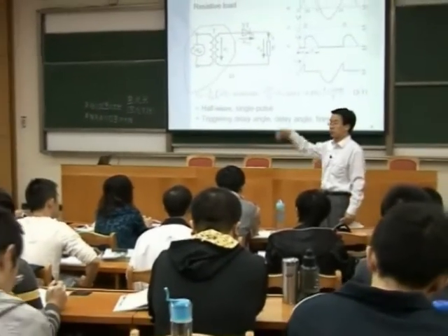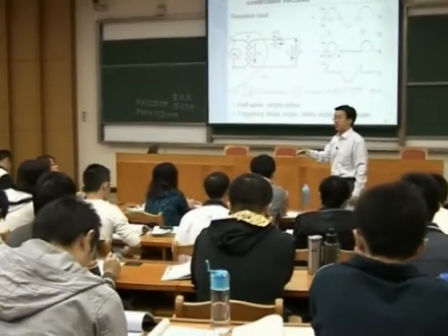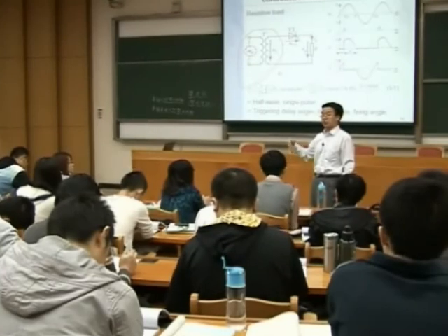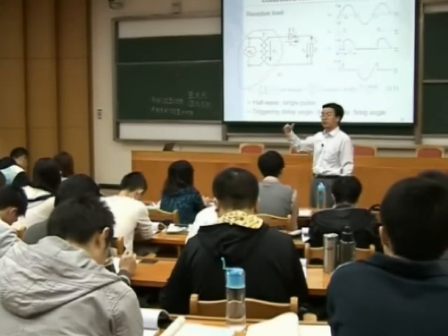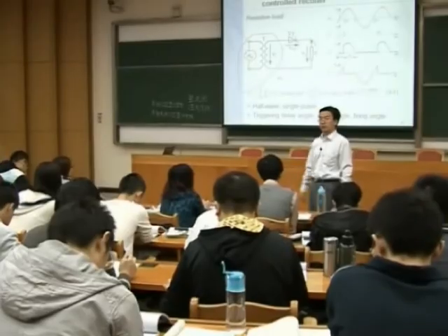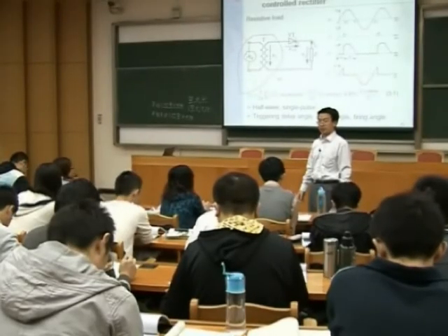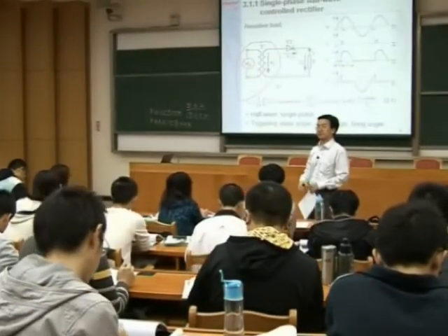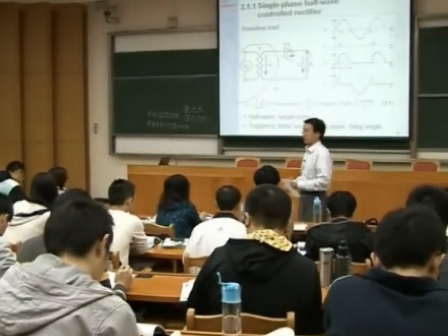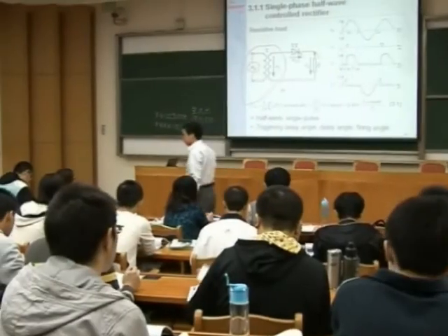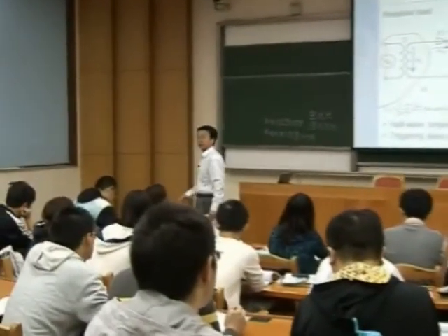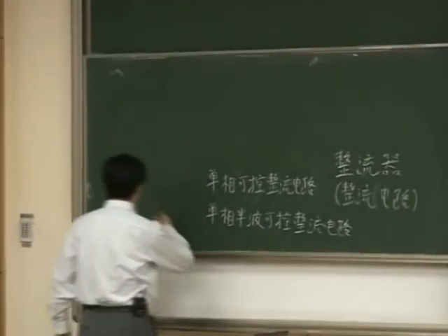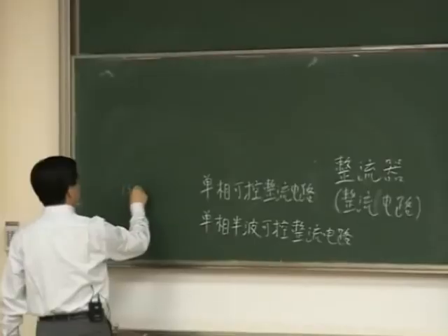If the input voltage is too high and the power semiconductor devices cannot deal with that high voltage, then we can reduce that input voltage a little bit through this transformer. Okay, what else? Can you guess? Isolation, right. Actually, I was going to put isolation as the first reason. We put the transformer here, the primary reason is for isolation.